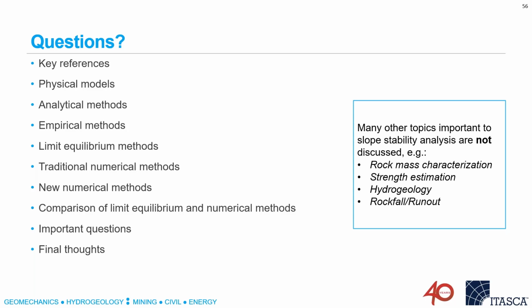And if it's clay, get some clay samples, at least do some Atterberg limits and get the plasticity index so we can estimate the friction. And just good photographs, good basic characterization: how much rock, how much soil, how thick is it.